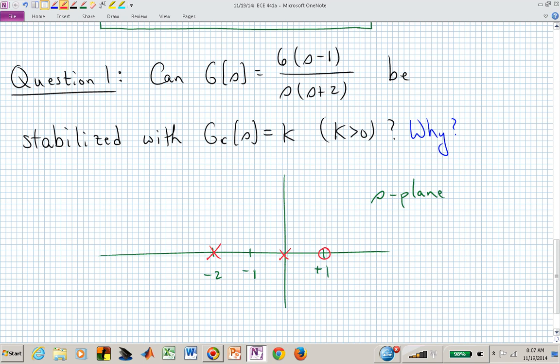Then you should quickly use one of your first rules, and you don't have to know the number of these rules, but now I'm looking for you to chop up the bread and determine which pieces of that real axis belong on the root locus. In this case, we have a segment between the origin and +1, and we have another segment to the left of -2.